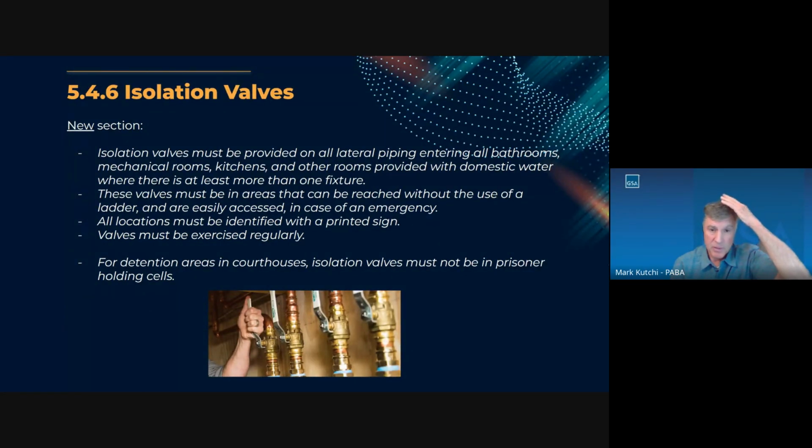So yeah, and the locations, like I said, is important. Without use of a ladder, it can be easily accessed. There should be a printed sign that shows the location of the shutoff valve, and this is more of a maintenance item, but valves must be exercised regularly. And then for detention areas and courtrooms, the isolation valve must not be in the prisoner holding cell, and probably should not be in the prisoner area, detention area at all. It should be outside of those areas.